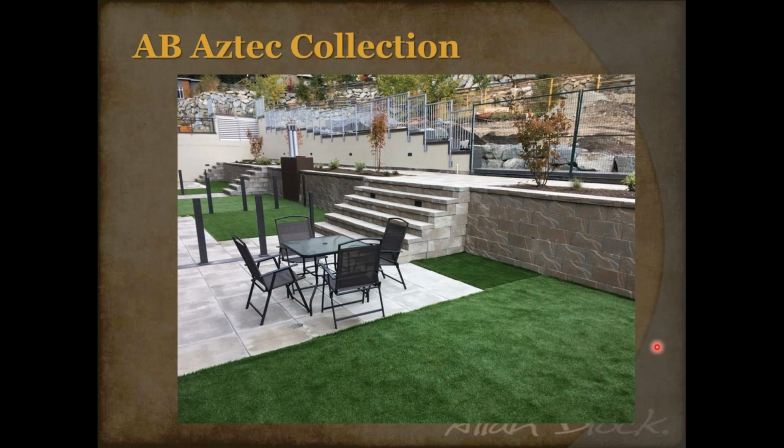I'll give you a couple examples. Here's a project that we did up in Canada. Again, it's with the Aztec collection, non-split, but you can see the fill steps in front of it, independent of the wall, and they just went ahead and did very abrupt steps, 12-inch step tread depths right up the hillside. And so that way they could make that transition.